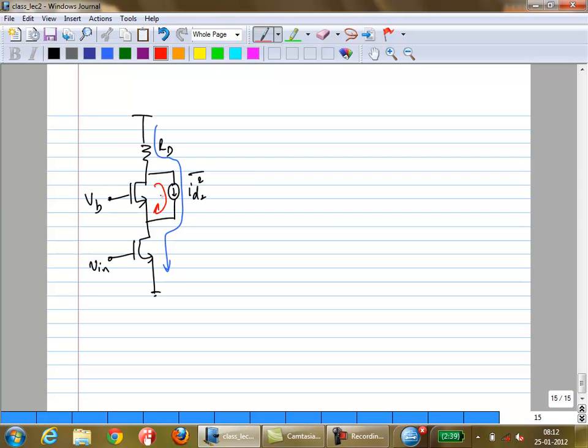So what do you think will happen in the case of the cascode? What can you say about the relative ratios of the two currents? Well, you can look at it two ways. So suppose you look at the current splitting in here. What is output impedance here, looking down? RDS1. What is the impedance looking out? Input impedance looking up? 1 by GM.